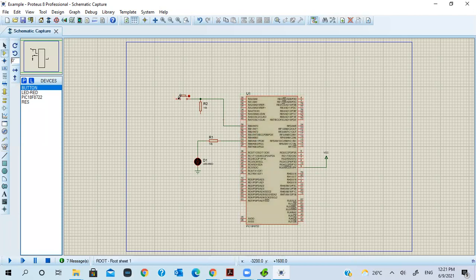Now, this button has to have a power source as well. Right? So what we can do is take this button. Now we just need to connect that wire, this button, to a power source. In this particular case, we can use the same power source as the VCC, right? Because we are supplying the 5 volt to the button. So whenever the button goes high, it will turn on the LED, right? There will be an input to port P0, right?